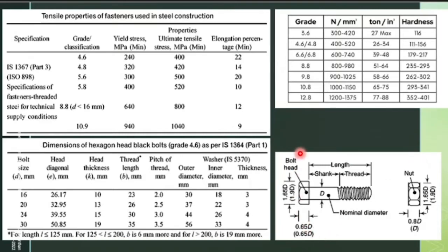Before going into the design of bolts, you should know the technical components of the bolt. You can see that this is a small component which you see day to day, but it has this much terminology. This differentiates the type of bolt. You will normally have a head portion, and as per the code book, IS 1364 gives the dimensions of the black bolt, which is the unfinished bolt. For each and every grade of bolt you have a code book, and they should follow these grades.